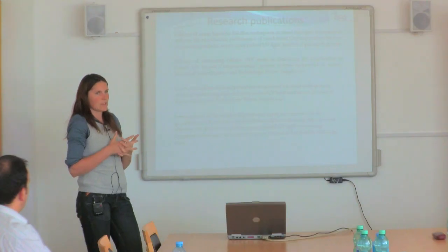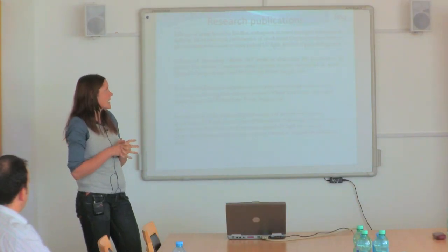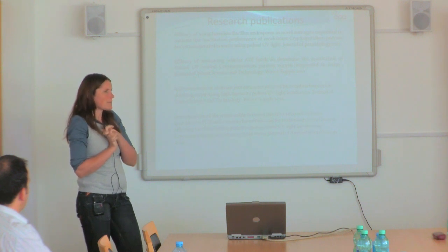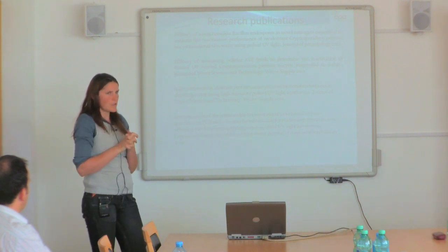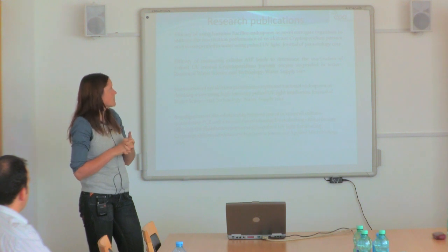My future work now will be to optimise it more for the Bacillus spores. I have another couple of strains that I want to assess to see if I can get a very suitable organism as a Cryptosporidium surrogate. I also want to look at different methods for determining oocyst viability post UV treatment, because the method we're using at the moment is based on cell culture and infecting cell lines in the lab, which is very time consuming and quite labour intensive. So ideally for the treatment plant in Tuam, we'd need something more rapid for viability assessment.